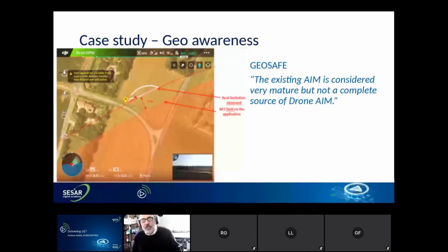And here we see that they were making some real tests using current geofencing implementation, looking at the current sources of geofence data, which was the conventional aeronautical information, and also the performance of current implementations of geofencing. And here they measured a drone as it flew around an existing geofence, and they saw that it kept a 17-meter or 50 feet boundary from the geofence.